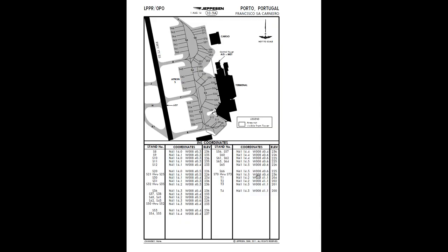Okay, here we are at the departure briefing, taxi and takeoff briefing. You have in front of you the charts of the parking in Porto, as you can see, Lima Papa Romeo and Porto, Portugal. We are actually at stand 7 Sierra 12. This is runway 17/35. Runway 17 is just up here, and the standard route for the departure is actually pushing back into the standard Sierra 2, and then following Sierra 2, Sierra 4, Sierra 6 and Foxtrot inside the runway.